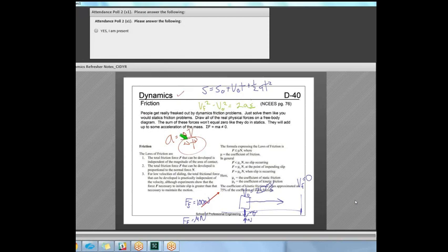Well, to get from the physical world of what objects we're dealing with, a tabletop and a block sliding around, to the time stuff like acceleration, velocity, and speed and distance, we need to know the value of A. So how do we find the value of A? F equals ma, right? So our force of friction is the only horizontal force that's slowing us down. So all I've got to do is give you the mass, and you're off and running.